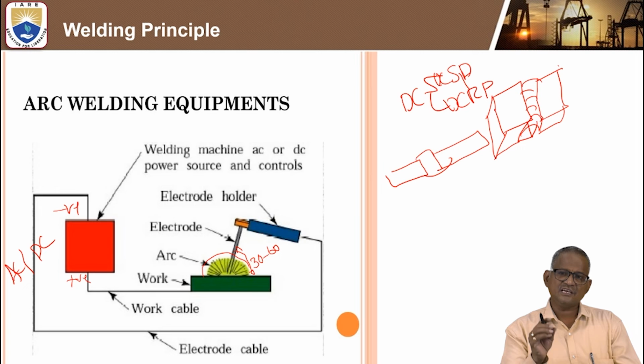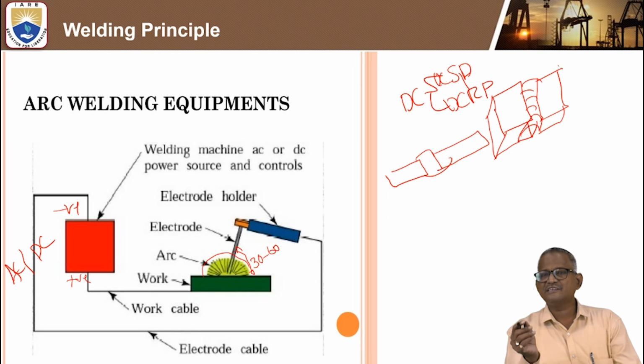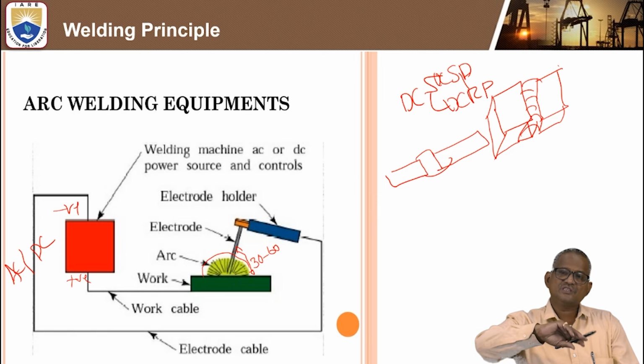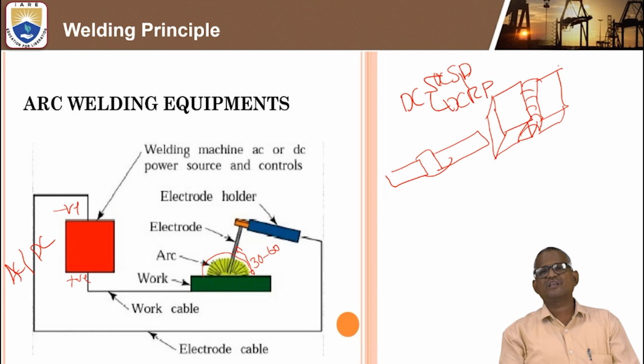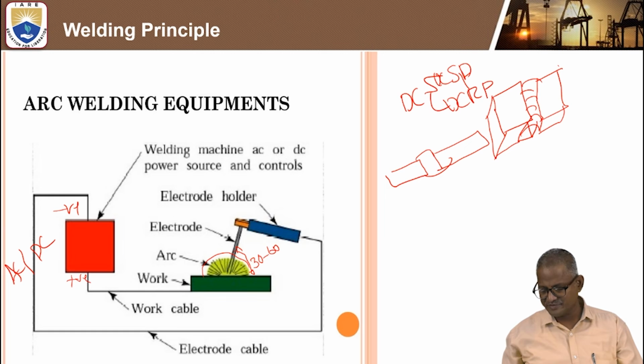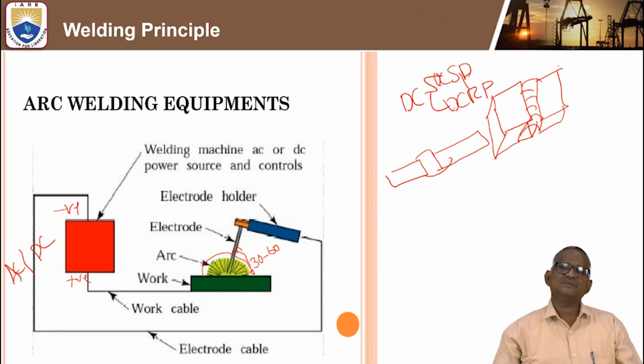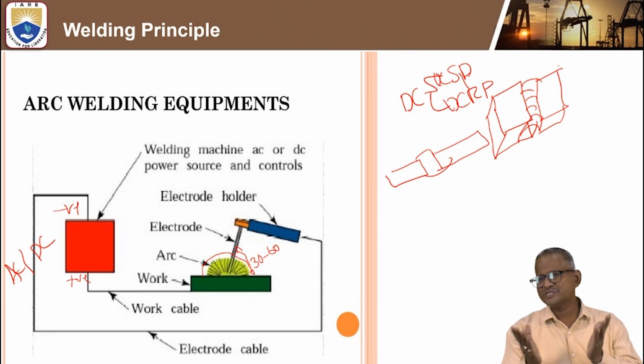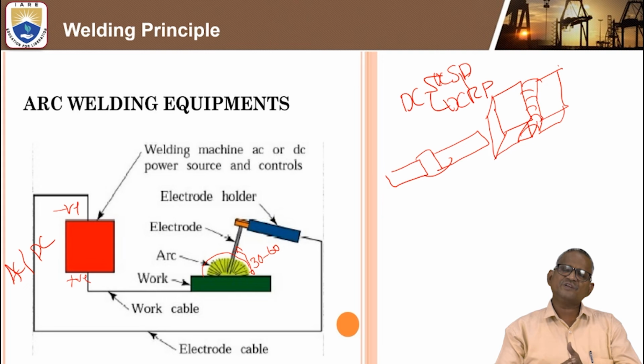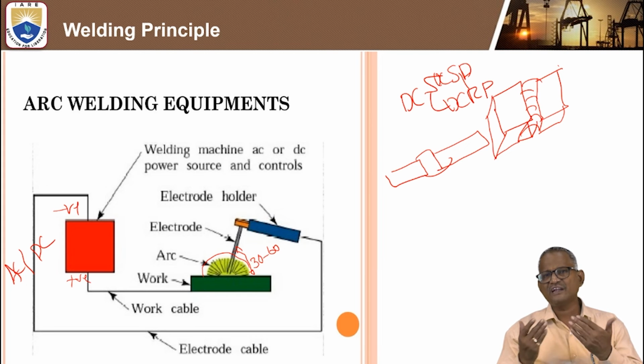And also you can see arc blow and how we will manage it. In some cases the arc will be very linear, sometimes more fillers or some extra oxides will be created. When it touches, it leads to an overflow, and arc blow also will occur. That leads again to some defects. So that is why a student needs to understand any welding technique. There must be some imperfections, which are in the form of welding defects.